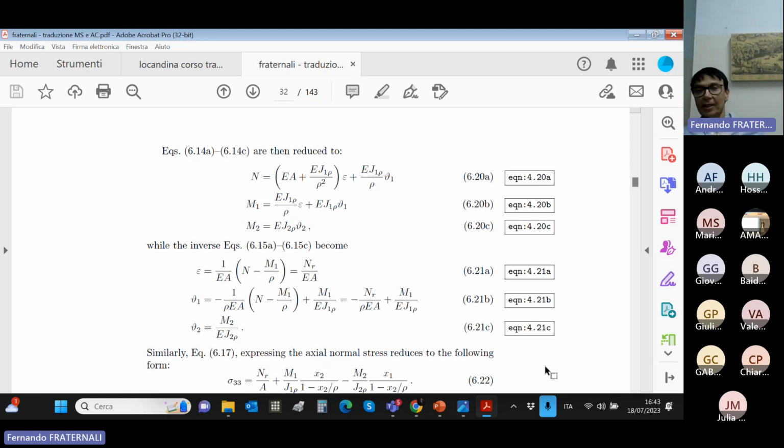So this justifies why we have named our course the mechanics, the mechanical modeling of curved and twisted beams, geometrically exact, because we can account for all the couplings in the equilibrium equations, in the compatibility equations, which are of geometric nature, and also in the constitutive equations, which are also derived from geometric considerations, but are usually ignored in normal curved beam theories.